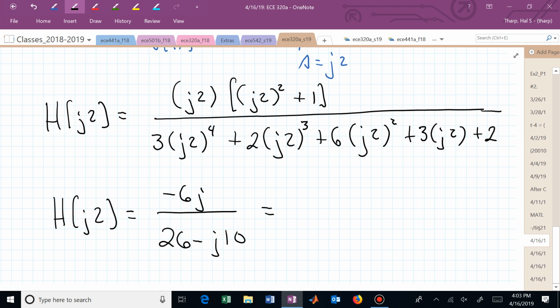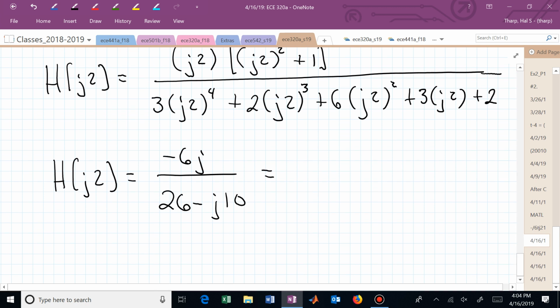This other one in the denominator, if you're interested in it as a complex number, you would walk 26 paces along the real line, and then you would go down vertically 10. And that gives you a vector, or a direction and an angle associated with the denominator at that location of j2 for the overall transfer function. Sketching that allows you to think about what this looks like as one complex number. Or you could divide all of that out. You could multiply by the conjugate on the numerator and denominator, however you want to do it, and you'll end up with h of j2 being